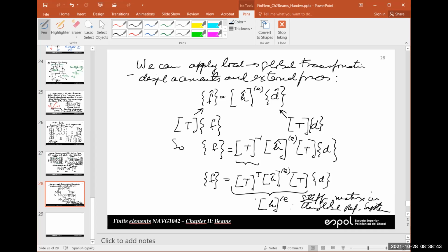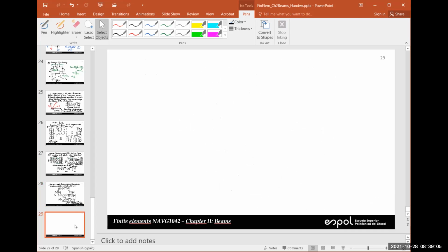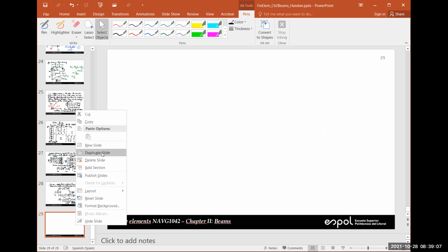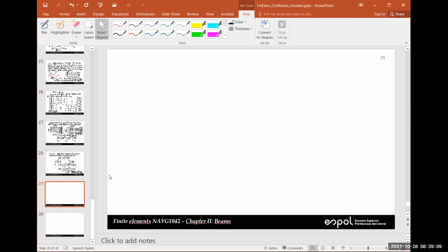So we're going to have 6 degrees of freedom for every joint. That's why we have to be very careful with the number of joints or the size of the elements, because the number of operations that we need to solve increases dramatically. That's why we need more and more computer power, because the number of operations is so large.